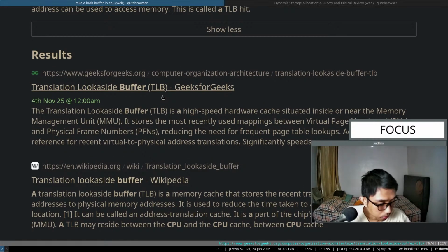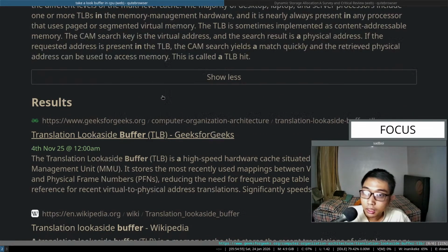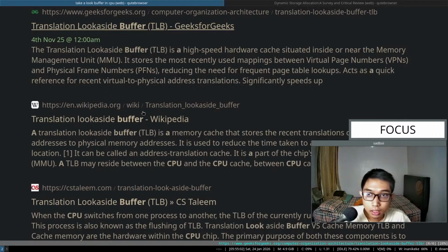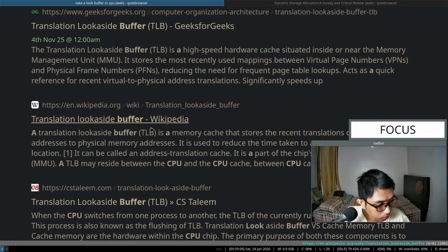Okay, so cache. Right. So the TLB or MMU is different from the cache that you're talking about? When you access a virtual address with a load or store, it goes through the MMU first to get the physical address.